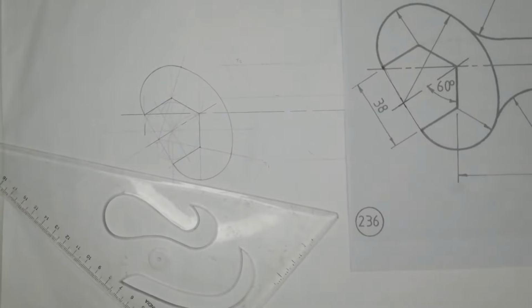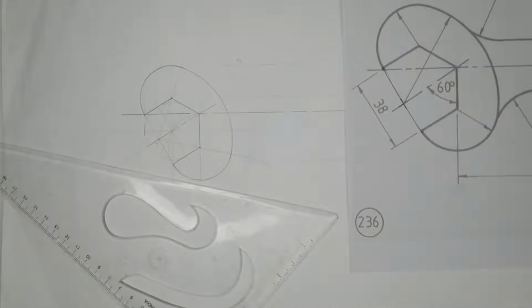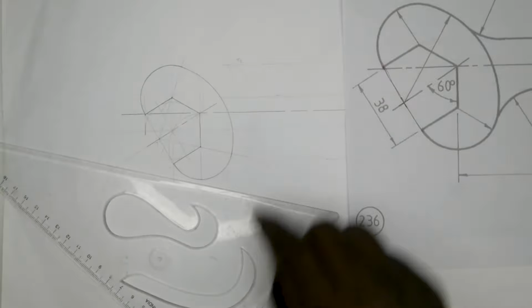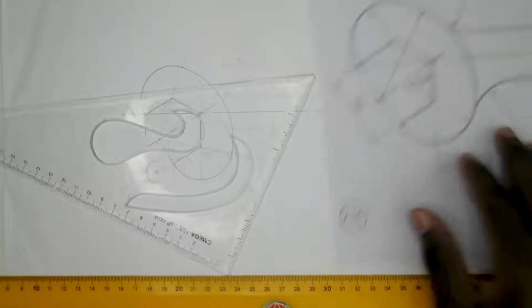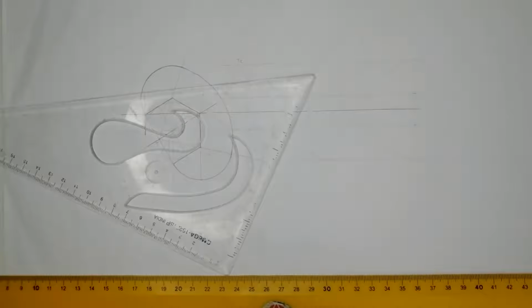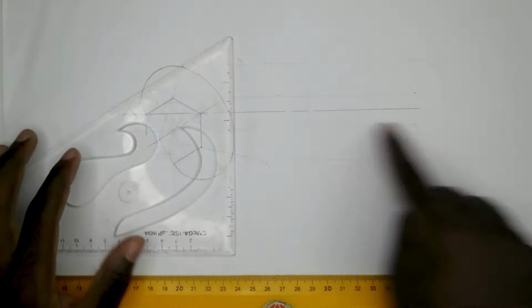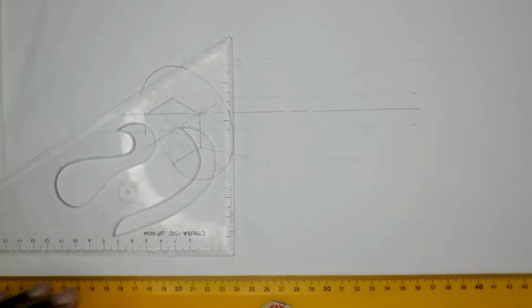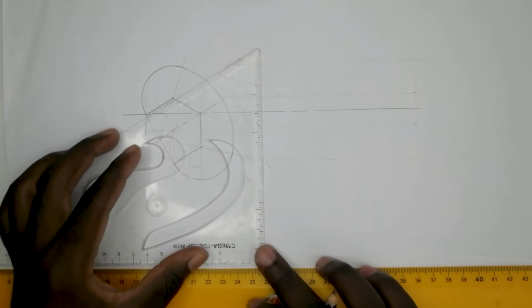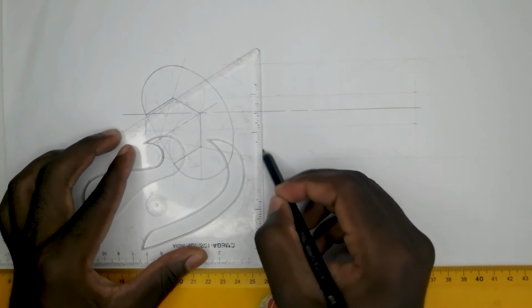You can see it's interestingly the same point where our area arc tangent with the center from T there is supposed to touch. The next thing is also knowing where our tangent is going to touch on the line. How we do that is you draw a line at 90 degrees with the line which the tangent is touching. So you can do that with just your t-square and set square. You draw it like that.